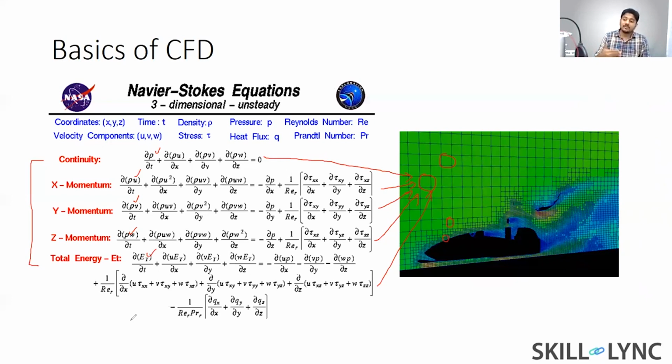That type of simulation is called direct numerical simulation. The number of computational cells that you need is roughly Reynolds number to the power 3. In your wind tunnel simulations, your Reynolds number is roughly 1 lakh. So that's basically 10 power 5. So 10 power 5 to the power 3 is 10 power 15, right? So that is 10 power 6 billion cells.